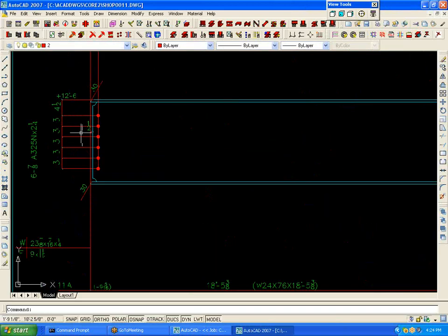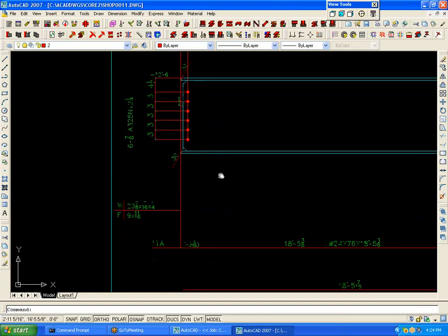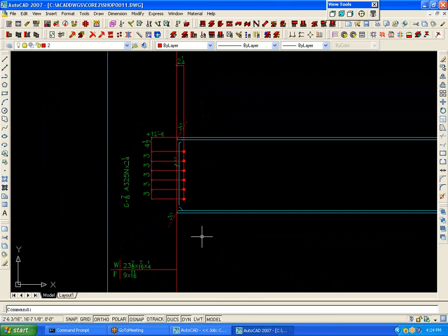There you can see the preps. Notice that the system cut the web back a 1/2 inch. That's again another clash. The fillet weld was 5/16 because it was a 1/2 inch thick shear plate for the moment connection. On a moment beam, there's only a 3/8 setback. Therefore, the beam only clears the weld by a 1/16, and there's no guarantee that the weld's going to be perfect in the field. It's probably not.